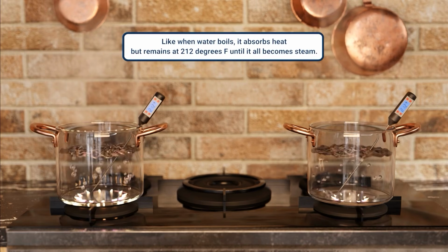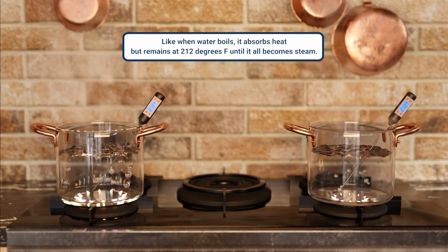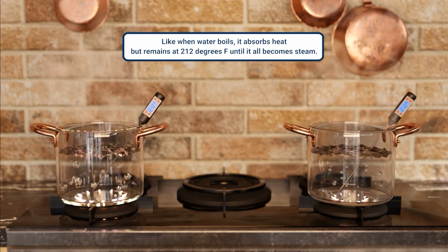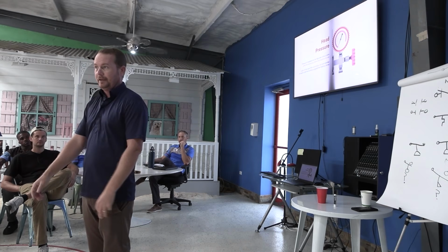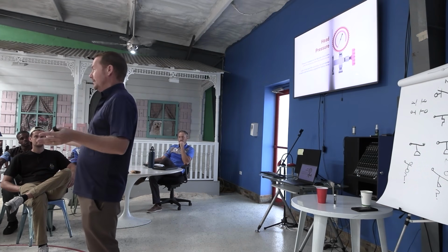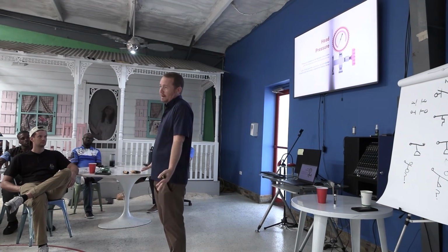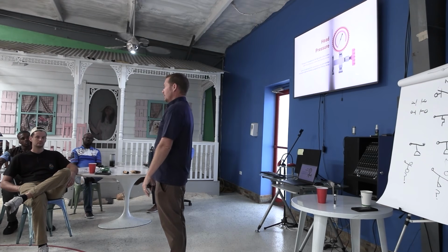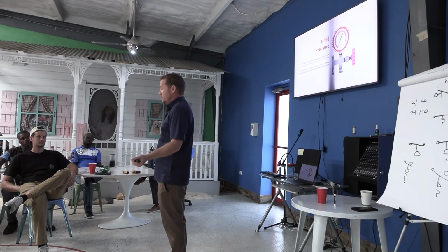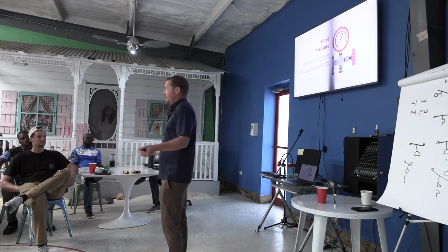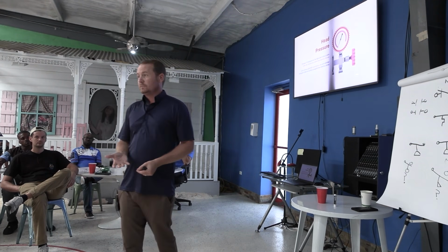That's our condensing temperature. That's our liquid saturation temperature, or high side saturation, whatever you decide to call it. It's condensing temperature. And why do we care about condensing temperature? Why does that matter to us? Because we can compare it to outdoor temperature and we can tell if it's normal or not. If it's elevated, that's not a good thing, right?